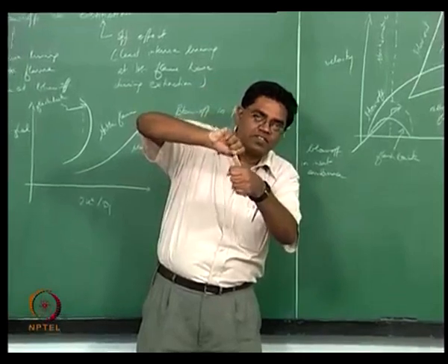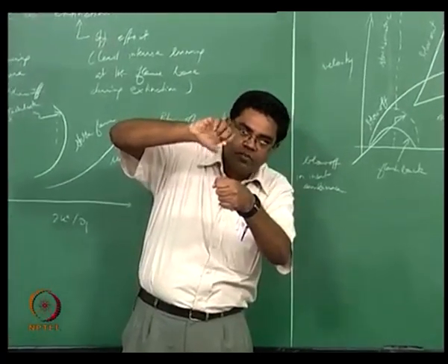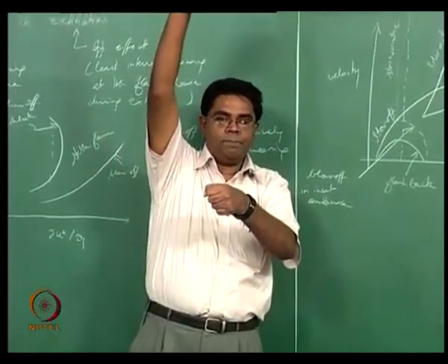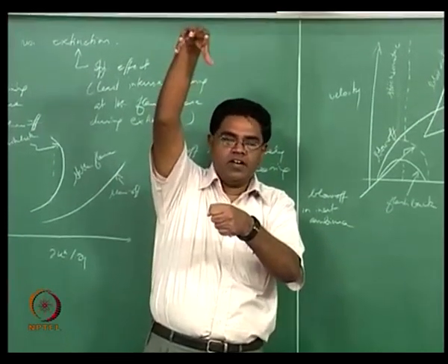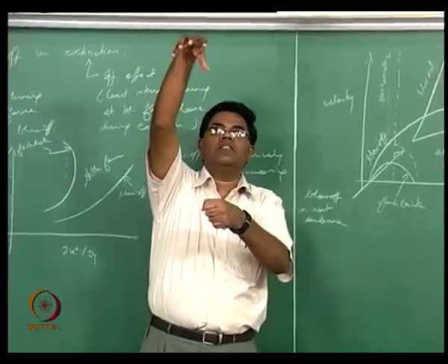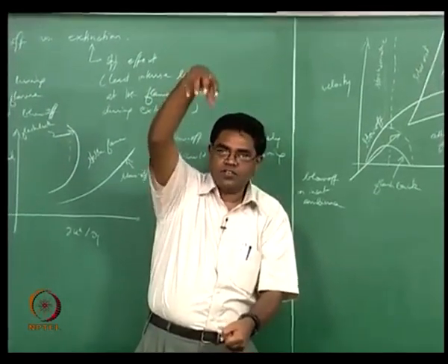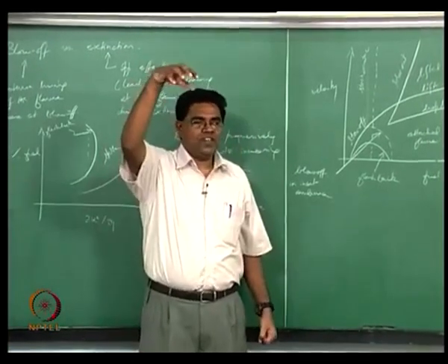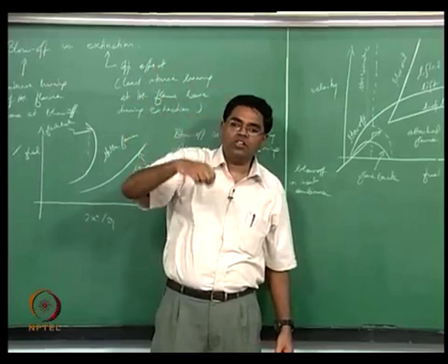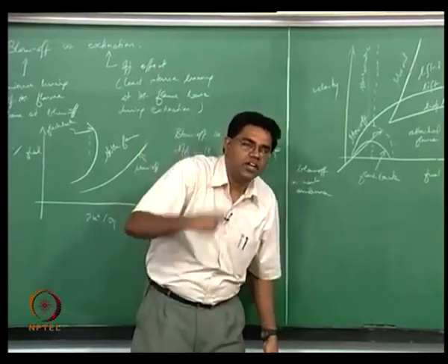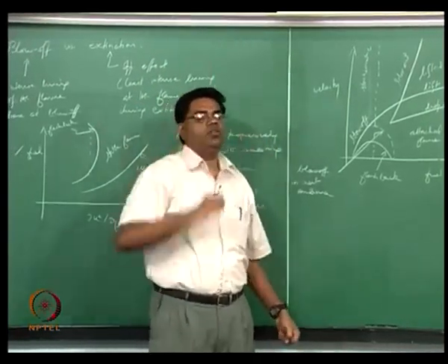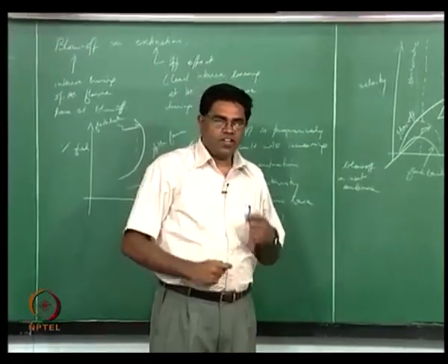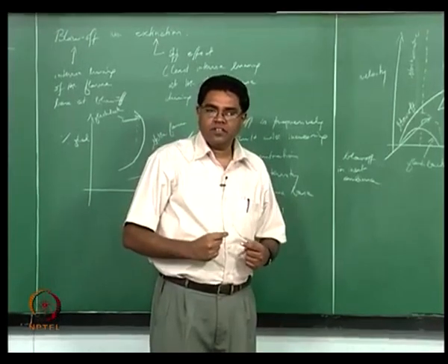So the flame is trying to actually get pushed a little bit further and further but still attached, and then it lifts, okay, and then it is actually burning there, and you're like, oops, let me just bring back the velocity so that it can attach. Nah, it won't. It would stay lifted until you decrease the velocity significantly lower than the point when you caused this lifting to happen. That's what is called a hysteresis, right?